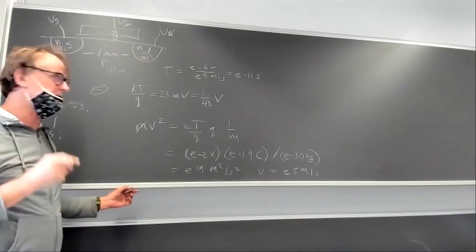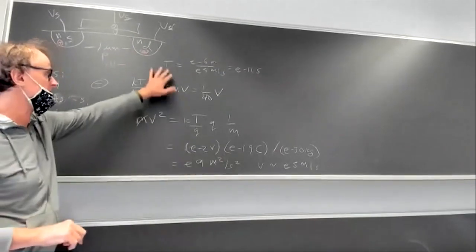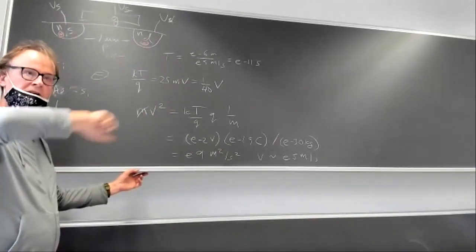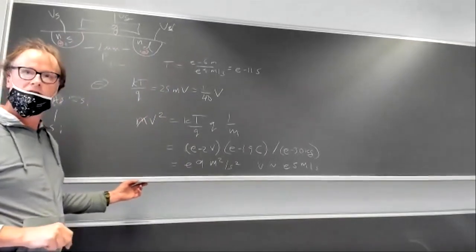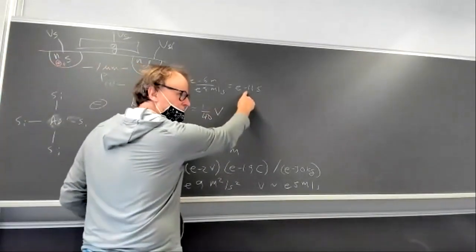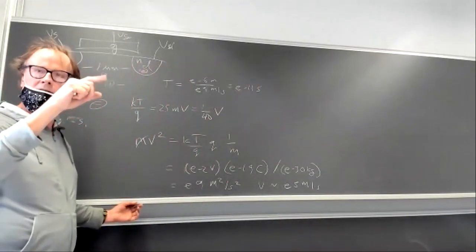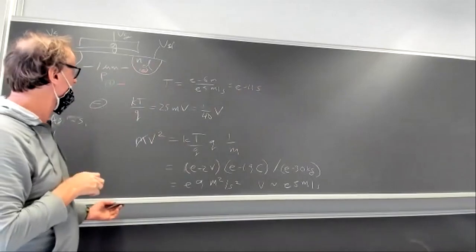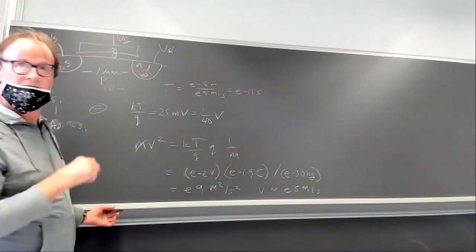Okay, I'm doing that because I want you to just understand what the scale of these things is, how fast things are moving around and what time scale you're talking about. That's 10 picoseconds if it was moving in vacuum, freely moving and not colliding with stuff. So it's a very short time, 10 picoseconds. That corresponds to a frequency of 10 to the 11 hertz, switching frequency. That's why silicon logic can work so fast, right? Because it's a short time it takes the carriers to cross the channels. I don't know if that's helpful.